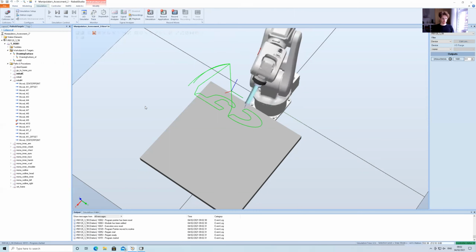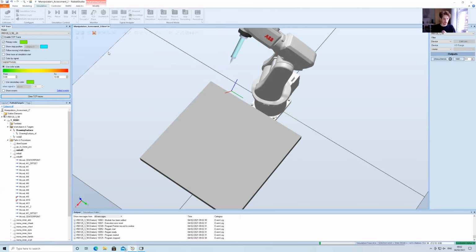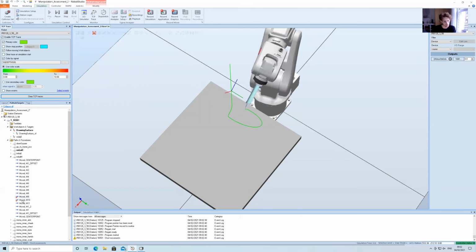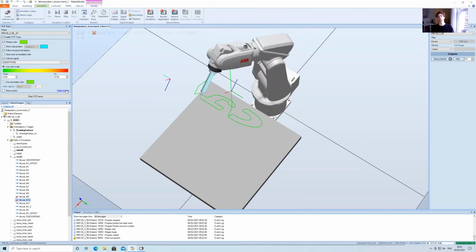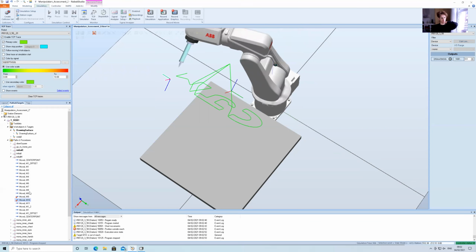Hopefully it'll be able to reach the, unfortunately the TCP trace lost where it should be. Hopefully it should reach all the coordinates of the letter M now. Oh, I say that, we do unfortunately have these. So you can see it requires some fiddling to make sure the robot can meet all of the points of a new work object frame, but absolutely possible. And as soon as those requirements have been met, you can run your programs in many different orientations that are not orthogonal to the world plane.